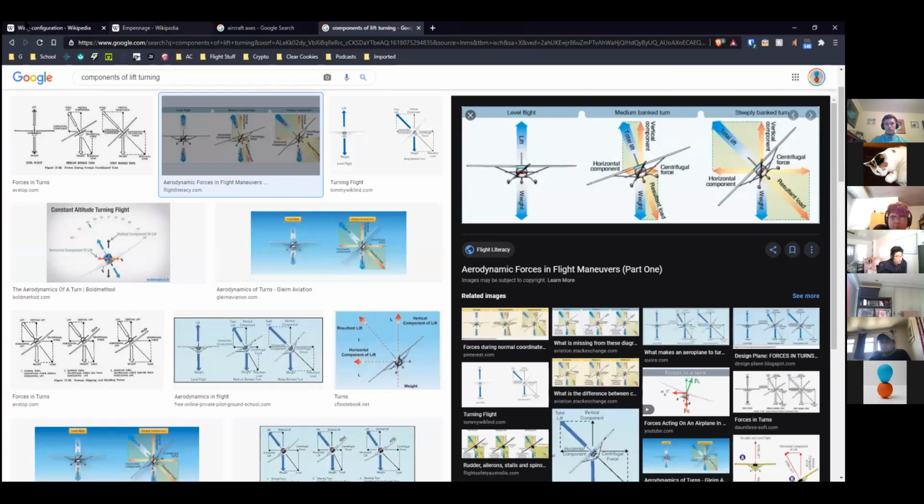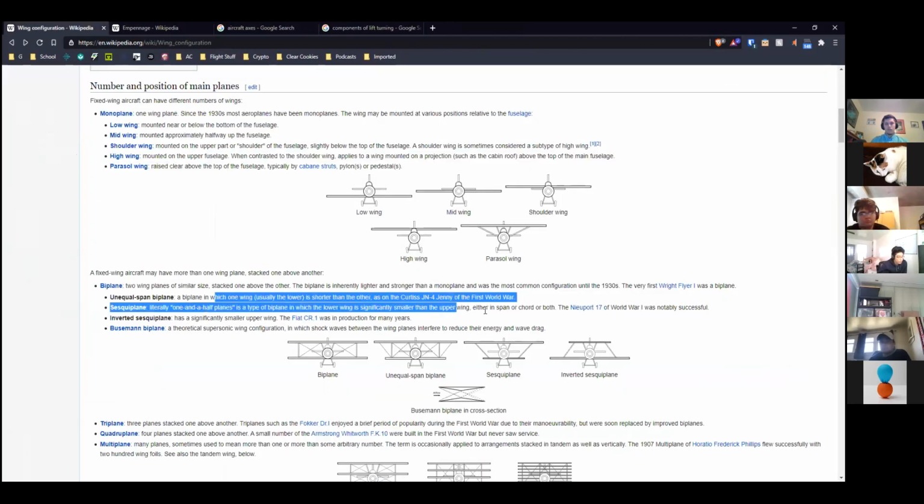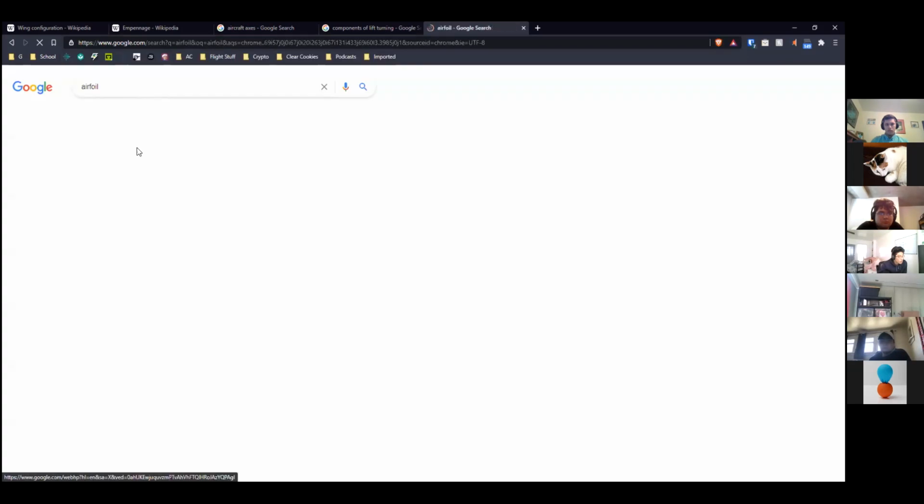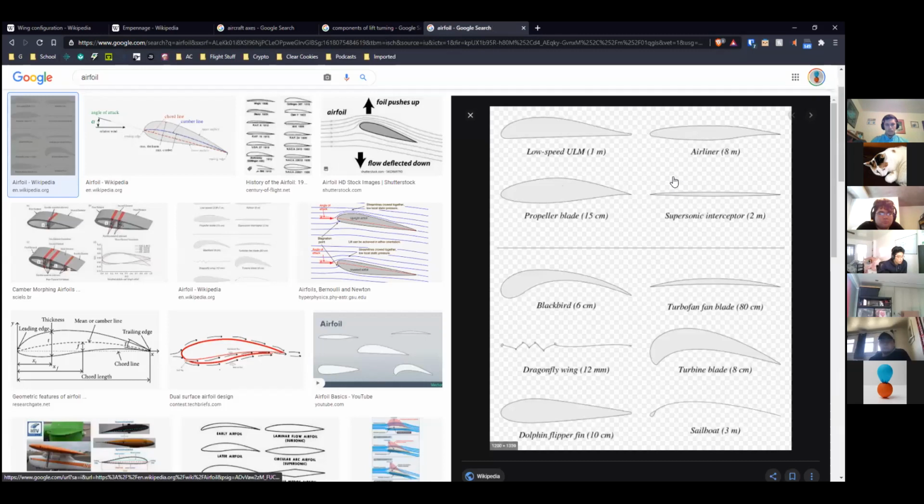As far as choosing the cross-sectional shape, that's called the airfoil, because I don't remember why. It's probably French or something. Airfoil Tools is a website that we'll use later. It's this kind of shape, the one that looks like that, and they heavily influence how your wing will fly, but you don't need to choose that to choose a configuration, because a wing with any planform shape can still have whatever airfoil you want.